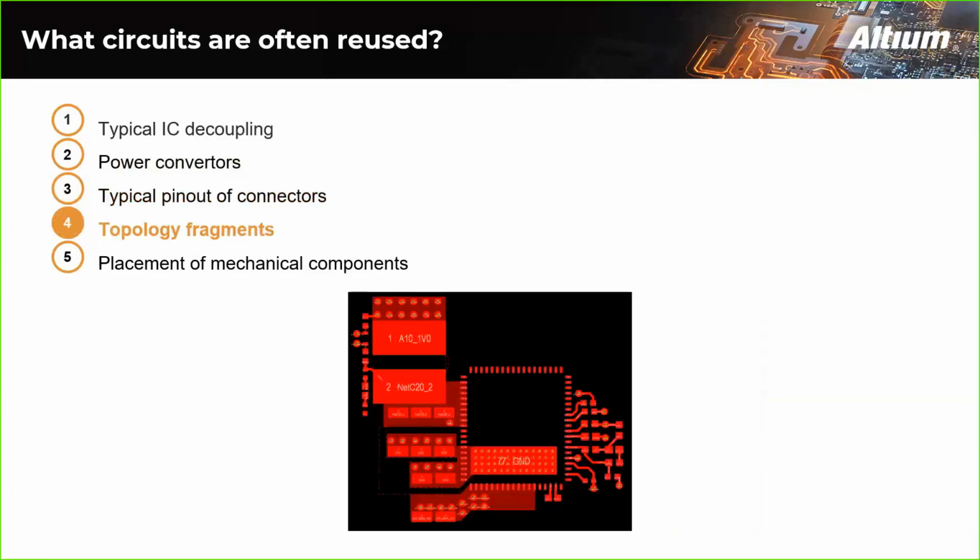The previous example was for the schematic, but using snippets, you can also place down parts of the PCB layout, including components, traces, and polygons. This works well if you had the layout for a USB connector that you use often. You can place it down and save yourself some time. And of course, you can always adjust if needed.